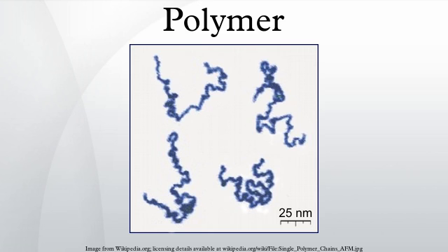Crystallinity. When applied to polymers, the term crystalline has a somewhat ambiguous usage. In some cases, the term crystalline finds identical usage to that used in conventional crystallography. For example, the structure of a crystalline protein or polynucleotide, such as a sample prepared for X-ray crystallography, may be defined in terms of a conventional unit cell composed of one or more polymer molecules with cell dimensions of hundreds of angstroms or more. A synthetic polymer may be loosely described as crystalline if it contains regions of three-dimensional ordering on atomic length scales, usually arising from intramolecular folding and/or stacking of adjacent chains.